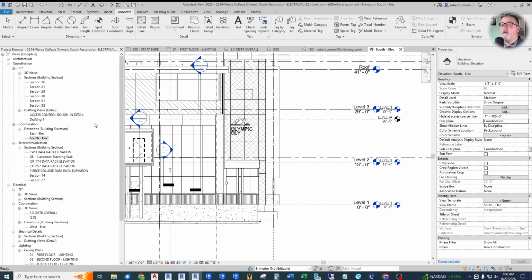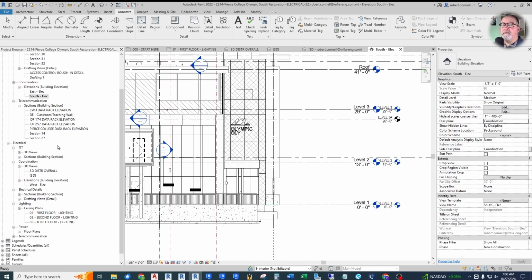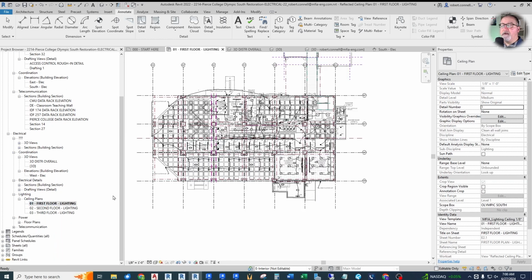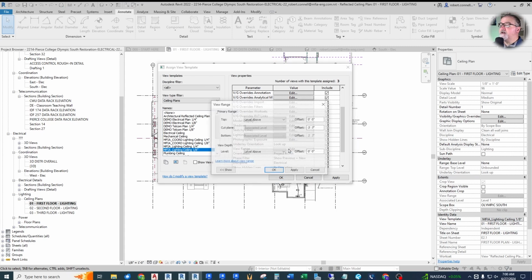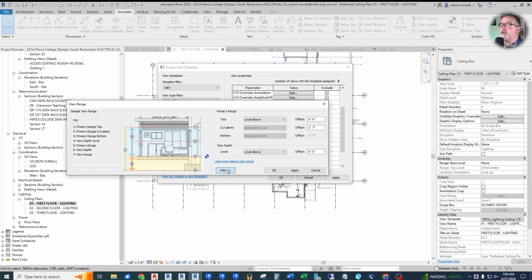And we say, I want that lighting floor plan to be based upon level 1. Down here, there's an associated level 1, and it's tied to that. Where does it cut horizontally, like a section, cut through the walls of this? That is determined by a thing called the view range. Right here, view range. If I edit that, if I show a little picture, here's a section of view range. So what we have is a lot of different things, but the main thing is this blue area.